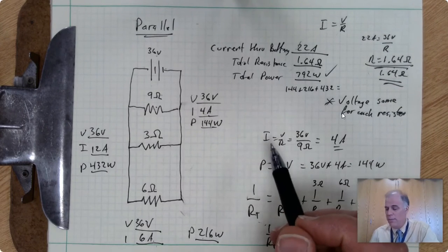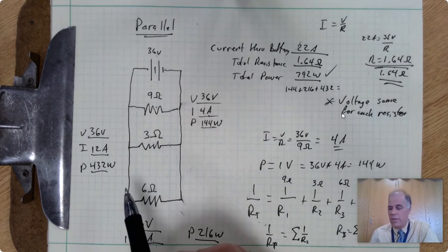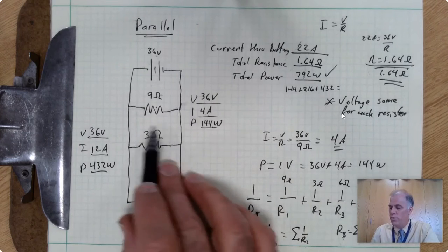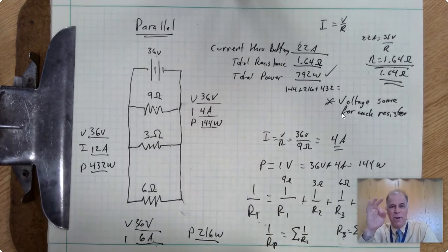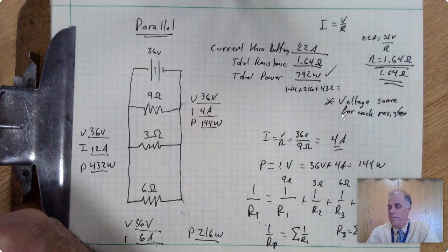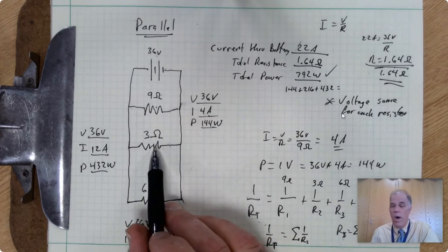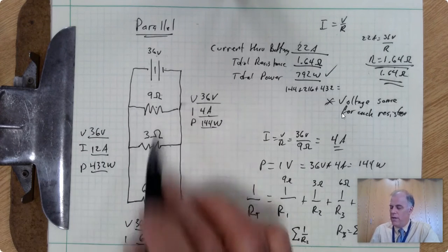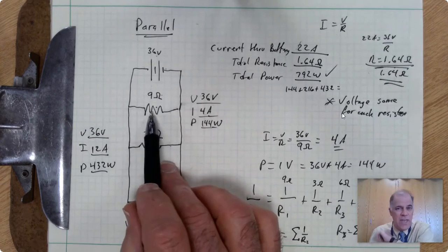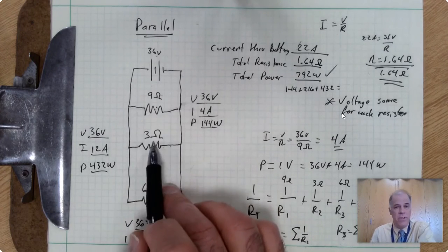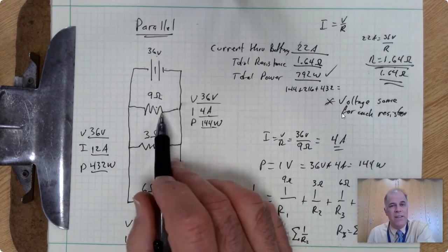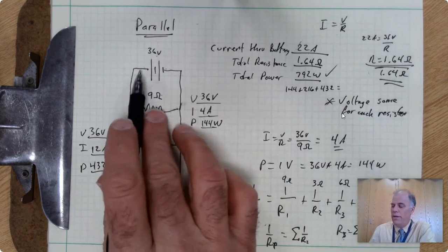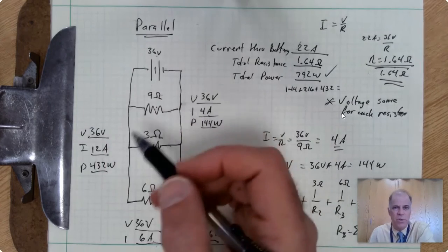This kind of makes sense because, again, if you think of it as plumbing, a sequence of pipes. If you have just a single pipe here, which is 3 ohms worth of resistance, that means it's got a fairly small diameter and it doesn't let very much water through it, right? But if you open up another pipe, even though it's an even skinnier pipe, a smaller diameter than this one, it's still going to let in a little bit more water. It's going to let a little more water flow through, which means that more water is going to be coming from the pump, if you will.